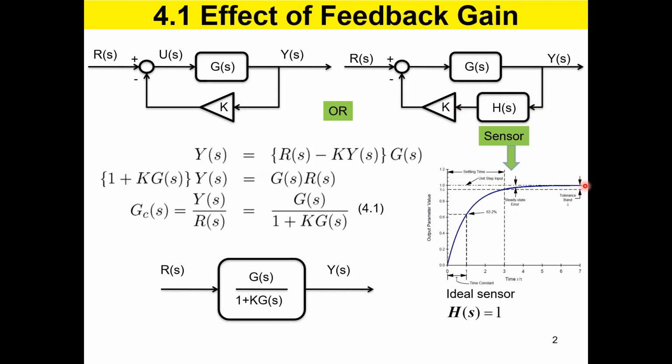Now, if you think of a sensor generating a response like this, it takes some time to actually give the reading accurately out of the sensor. And if you read the sensor before that, you get misled. So therefore, this is an issue. You need to keep an eye on whether the sensor is stable or not. If the reading is changing, you know that it is not correct, and you have to give time until it gets over here. Only when the value is settled down do you read it. So this is additional overhead of using sensors.